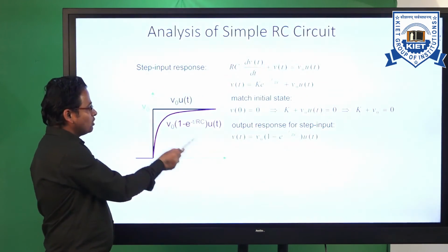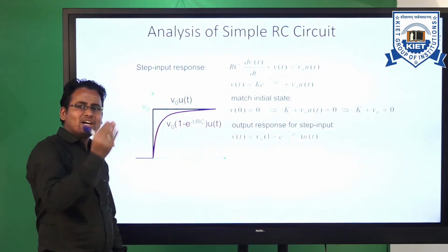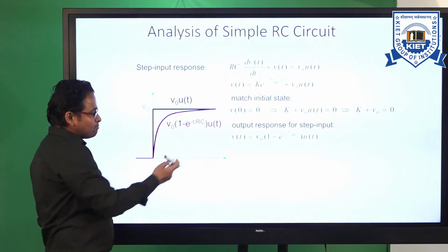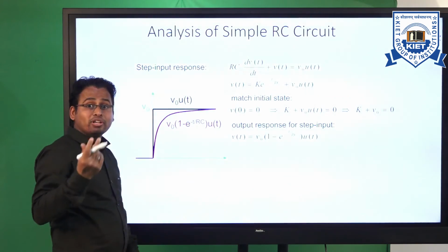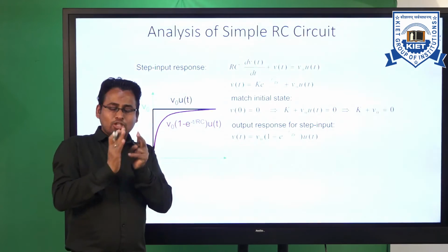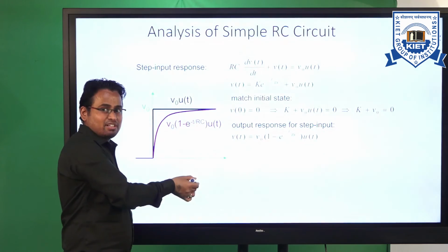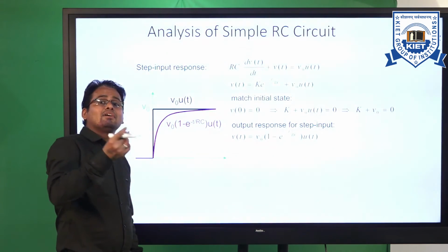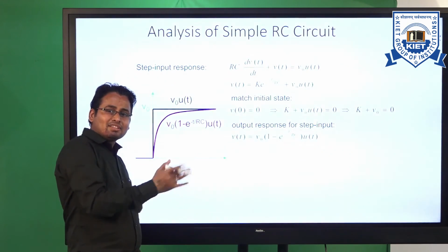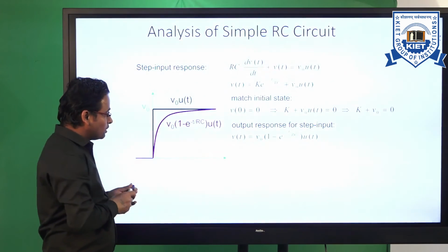So that is the response, the V naught versus t diagram. In this particular diagram, again we are seeing the transient state and steady state analysis. After a 4T time interval, I am again saying 4T. T is the time constant. After 4 time constants, the response will approach the steady state response. Okay. So 98% of the response is reached at the 4T interval. There is a plus minus 2% difference. So after the 4T interval, the steady state comes. That response is also indicated. Now come to the next.